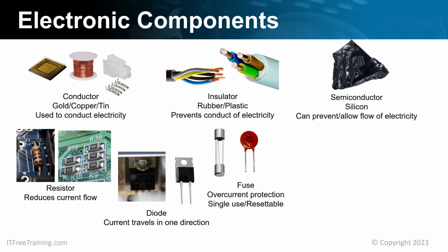These fuses are made of materials that will break the circuit if the current gets too high. However, after a period of time, the fuse will reset itself and allow current through again. A lot of these are temperature-based, so essentially, when too much current goes through, the material heats up, breaking the circuit. When the temperature returns to normal, the circuit is restored.